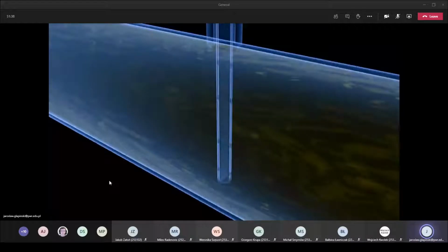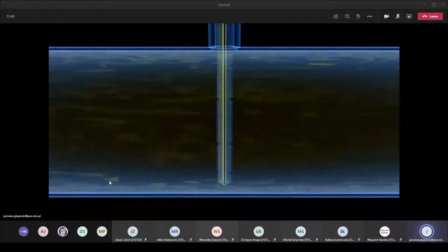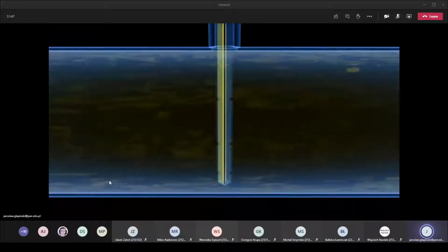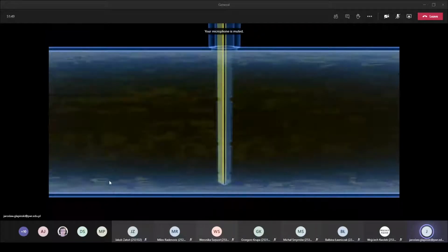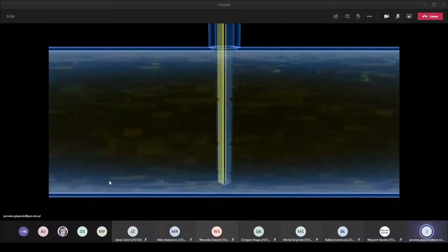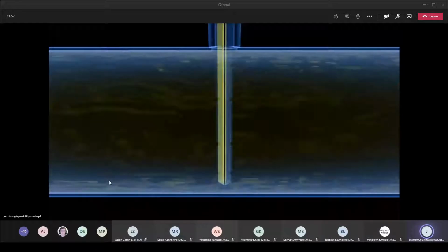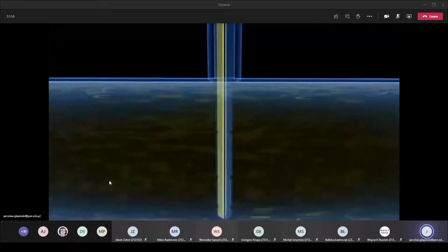If the fluid is not flowing, the pressure before and after the probe is essentially the same. As soon as the fluid starts to flow, an additional impact pressure against the front of the probe is generated, also known as the dynamic pressure. On the rear of the probe, in contrast, only the static pressure, which is not related to the flow, is still measured.